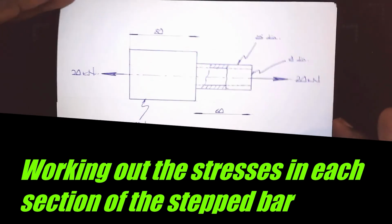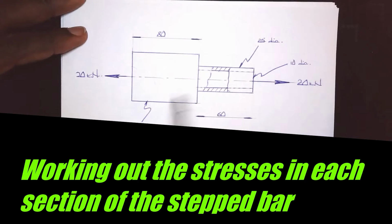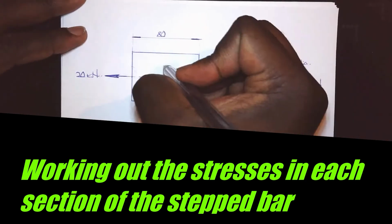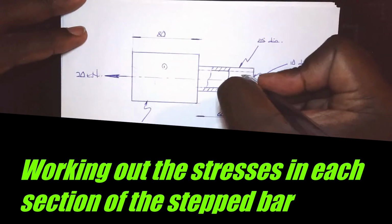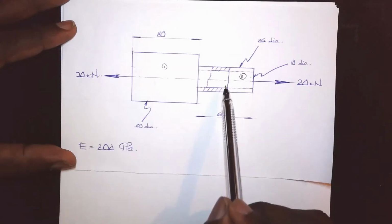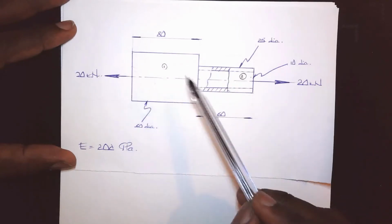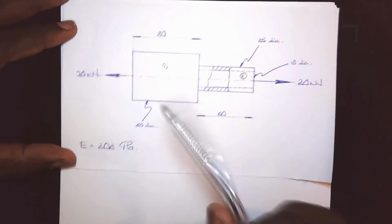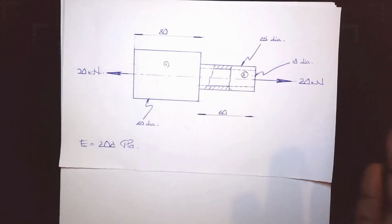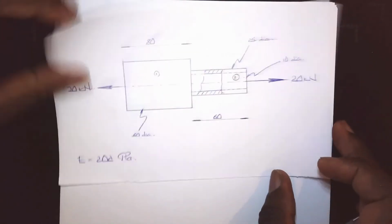Let's go through this problem. This is a diagram of the step bar that we have. We've got two sections. Let's call this part section 1, and let's call the hollow part section 2. What we're going to do is figure out what the stress is for section 1, and use that information to help us find out what the stress is in section 2. Once we figure out the stresses, we can then calculate the elongation for each section, and add the two to get the total extension experienced by the component when subjected to a force of 20 kilonewtons.